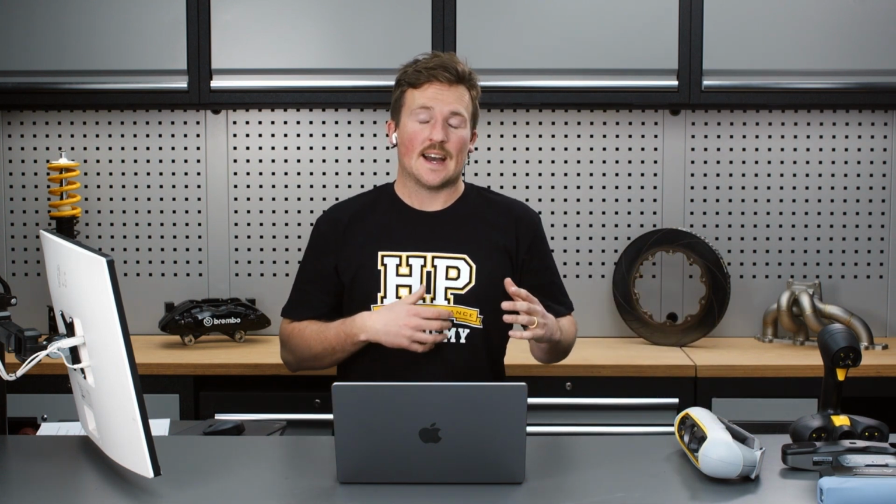So, structured light scanners, depending specifically, the white structured light scanners have a lot more trouble with reflective surfaces compared to the blue structured light scanners. That's a bit of an improvement because of the wavelength of the blue light, and then from there the laser scanners actually work with reflective surfaces a lot better, basically just because of the intensity and the wavelength of that laser light beam, so that helps a lot there.